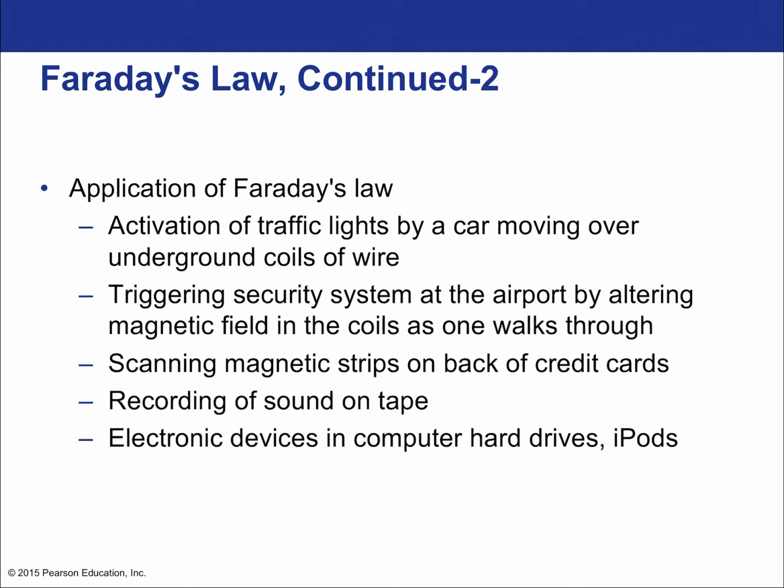Okay, so application of Faraday's law: activation of traffic lights by a car moving over an underground coil. That's where you see where they cut out the road to add in those coils. Those are for automatic traffic lights. They work on induction. There's a lot of inductive chargers these days. A lot of phones are charged by inductive charging. You don't have to actually plug anything in. You just rest the device on top of a platform.